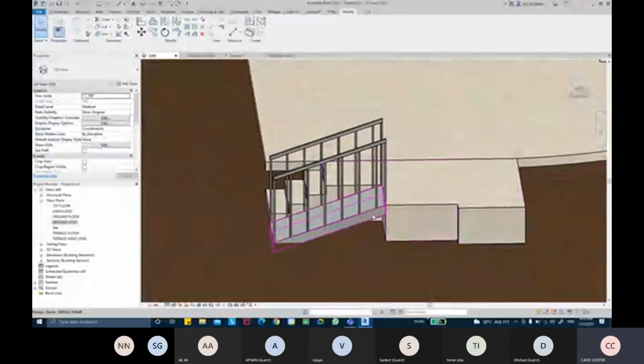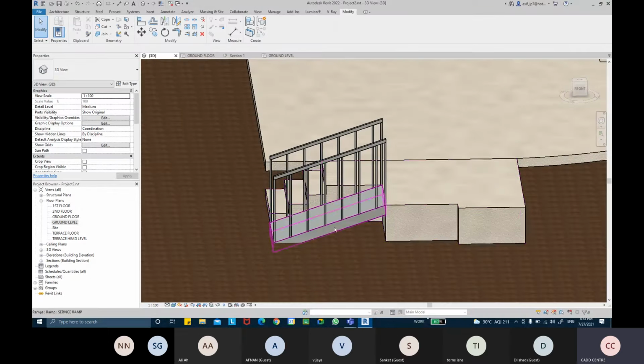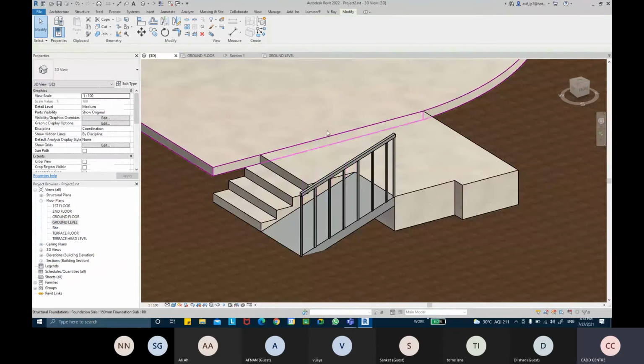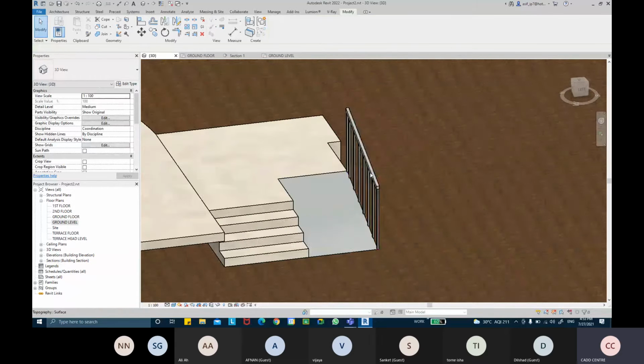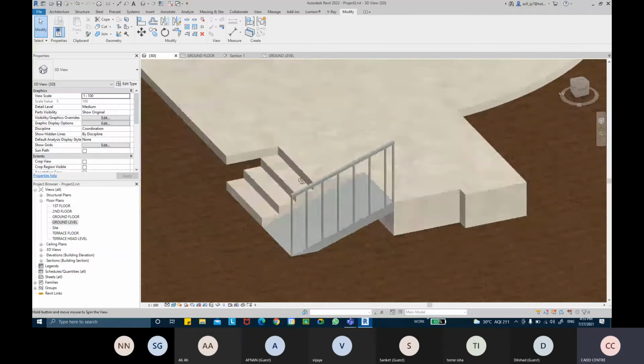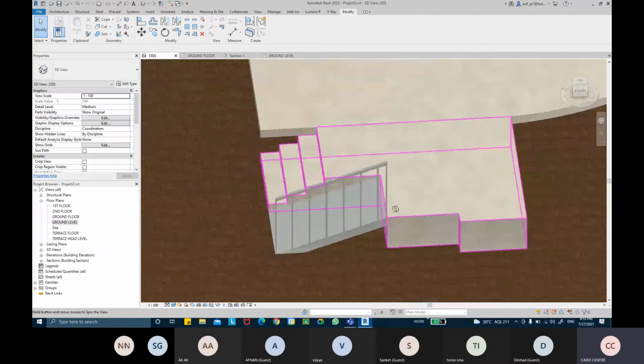Looks great. But still we have a little problem at this end as well. It's not a boxed ramp there. So if you wish to delete this railing right now, we can delete it off. We don't need to add a railing on that side. We'll keep the railing on this side, but later on we'll edit that railing as well, because this railing will be extended till the back. So I'll do that later on.